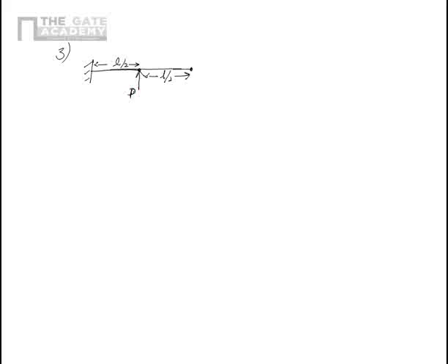Now again, assuming that the Young's modulus is E, etc, etc. Now let us see how to get the deflection for this beam. But before we solve, let us see how this beam is going to behave under the force. So when the beam deflects, it becomes like this. The beam will deflect like that till the force is applied. Beyond that point, because there is no force, that portion of the beam will simply rotate.